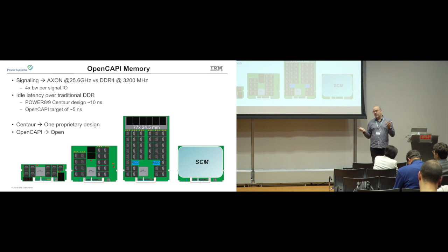And so we're able to run this very short interface at 3200 quite easily. And when we get to DDR5, when people are trying to run extremely high frequency DDRs, we'll be able to do that, right? So compare driving a signal from here to here, or the longest one just to be fair, the higher distances. Imagine trying to drive high frequency signals from there to there versus from a processor chip through the processor package, through the motherboard, through a DIMM connector, and up across the motherboard to the buffer chip. You would never go directly from the processor all the way to the memory device at DDR5 frequencies anyway. So you have to have some kind of buffer on the DIMM.